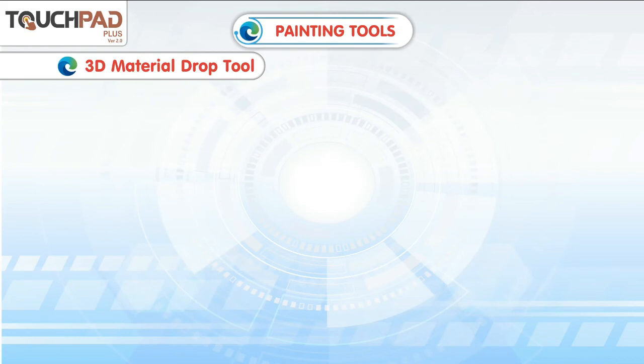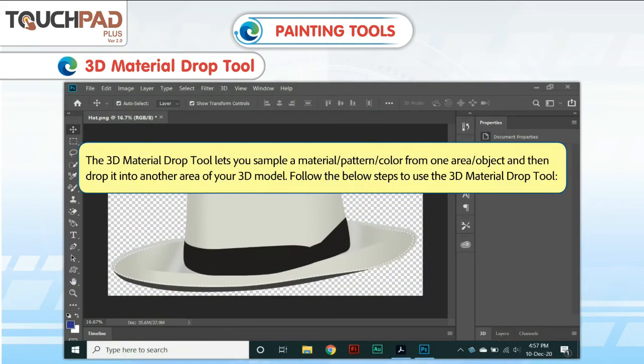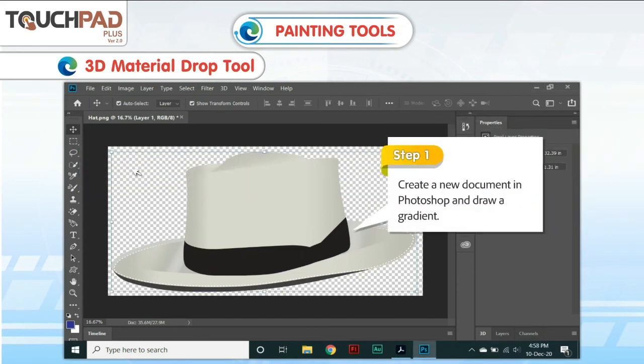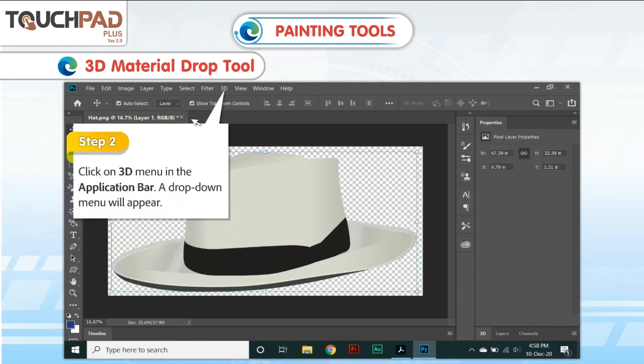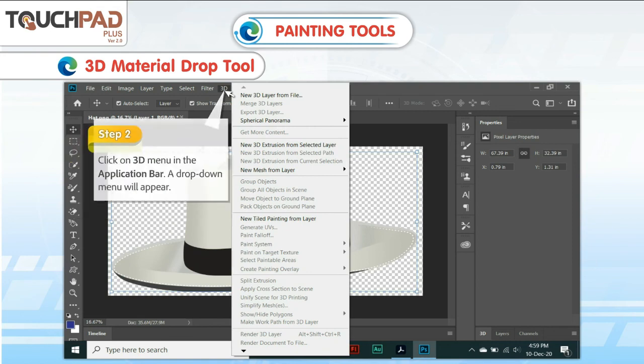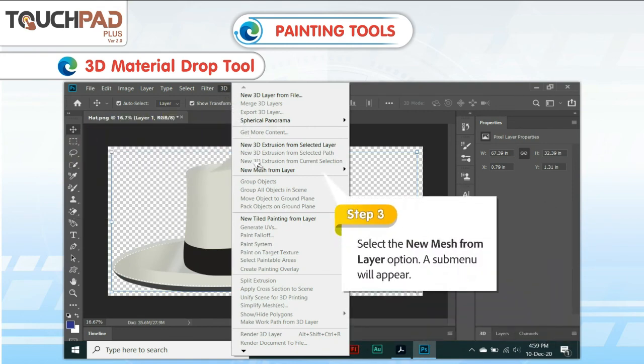3D Material Drop tool. The 3D Material Drop tool lets you sample a material, pattern or color from one area or object and then drop it into another area of your 3D model. Follow the below steps to use the 3D Material Drop tool. Step 1. Create a new document in Photoshop and draw a gradient. Step 2. Click on the 3D menu in the Application bar. A drop-down menu will appear. Step 3. Select the New Mesh from Layer option.